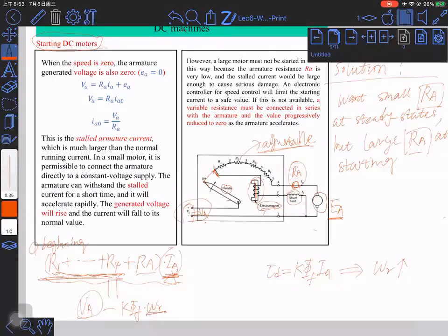So how do we do this? Say we cut off R1. The electromagnet will be further energized, and then this handle will be attracted to position 2. And if it's at position 2, obviously R1 is cut off because the current at position 2 is flowing in this way. It's coming out from the positive polarity, going through R2, R3, R4, RA, and coming back.